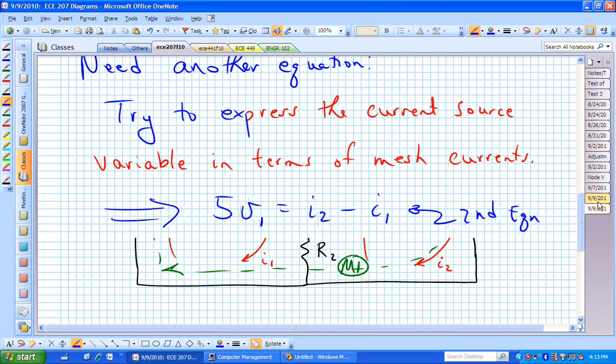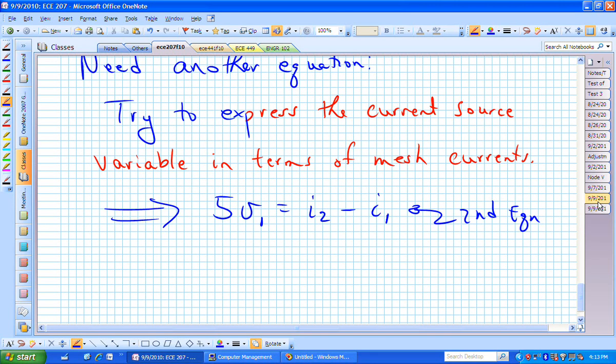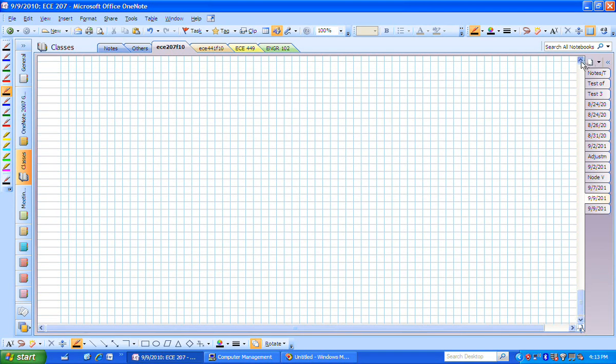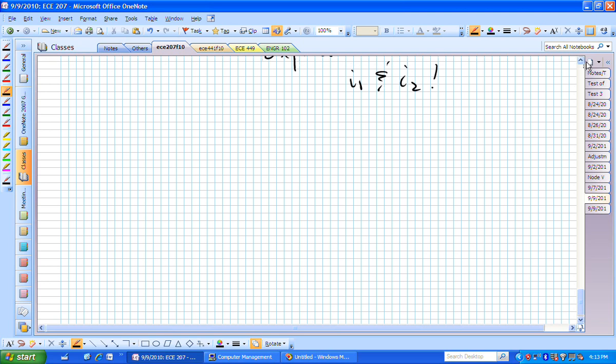If we go back, then I need to express this dependent value in terms of I sub 1 and I sub 2. And I think what some of you are seeing, hopefully others see it later, if not now, but V sub 1 in terms of I sub 1 and I sub 2 was simply R sub 1, I sub 1.